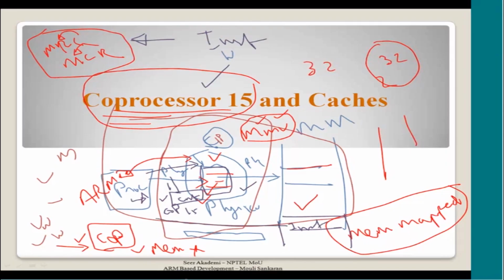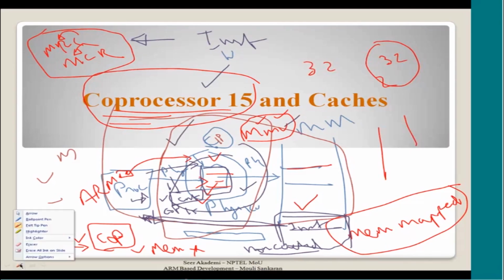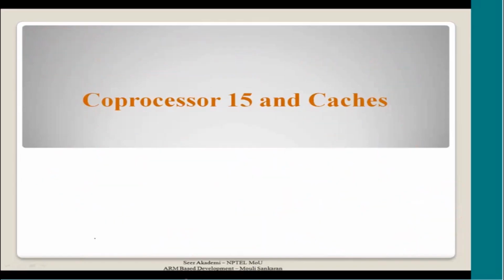So they have to be mapped without a cache. These are all non-cached items. This is some part of the initial memory which is accessed for configuring the cache controller and MMU. They are all non-cached, so these instructions can be directly accessed. So the cache will not be coming into play at all. And then the processor will configure the cache, then it will enable the cache. That is the flow of things, which you will understand better when I talk about the MMU.